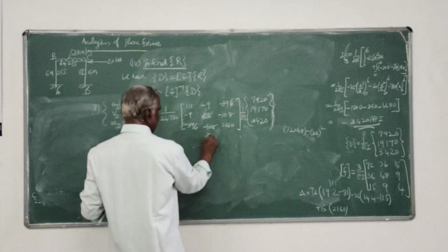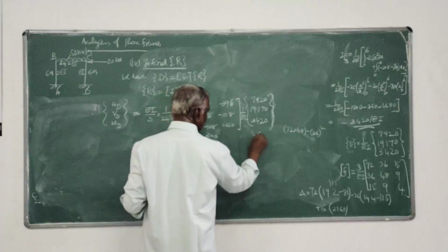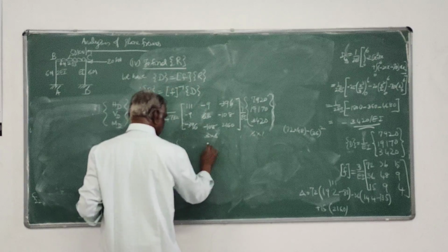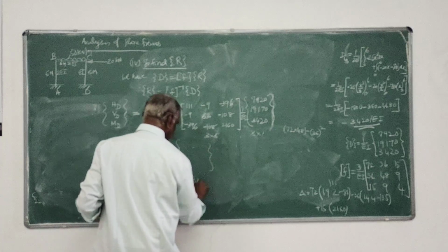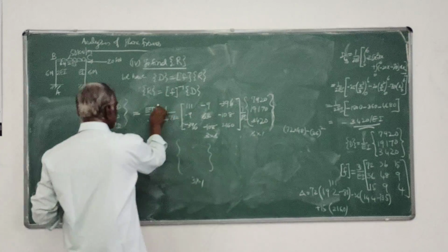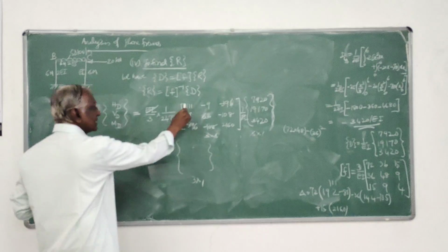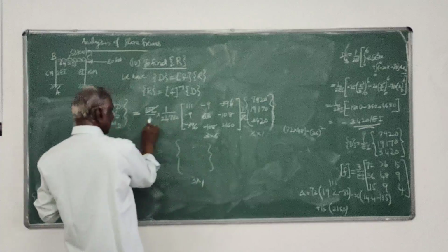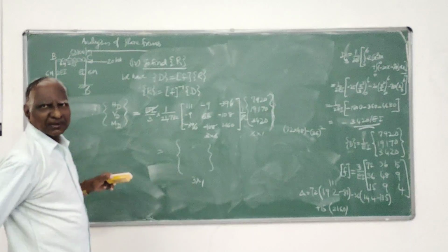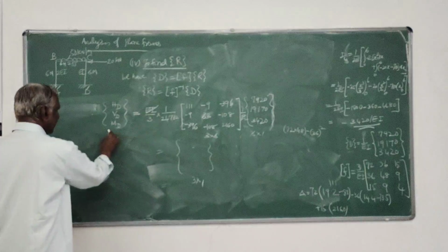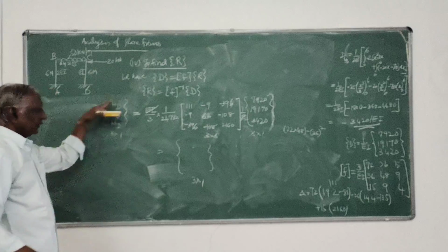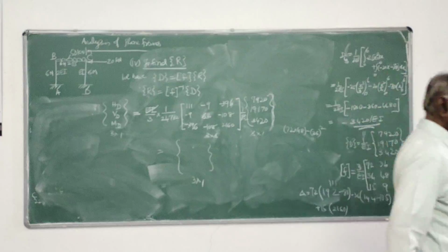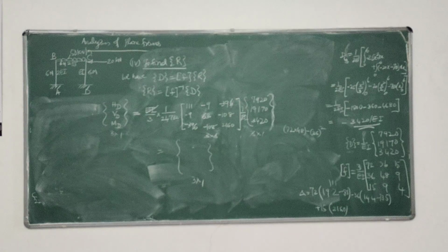So this is 3 by 3, this is 3 by 1, so the resulting will be a 3 by 1 matrix. This 1 over EI will go. This into this, minus this into this, then this into this, divided by this. And you get that is 3 by 1. You will get the displacements. Let me check that result.